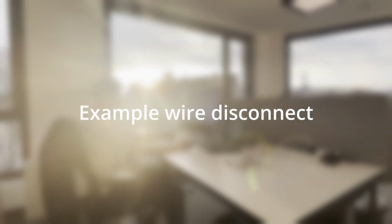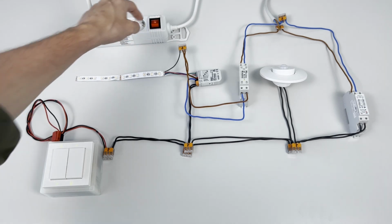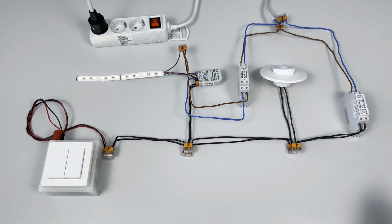Practical example, wire disconnect. Now that we've covered the theory, let's look at some practical examples. This setup includes CS sensors, an MC input device, a 250 milliamp DALI power supply, a 24 volt dimmer, and an LED strip. If your DALI 2 power supply has a test button, you can use it to send a max or off signal, or use it to send a test sequence.